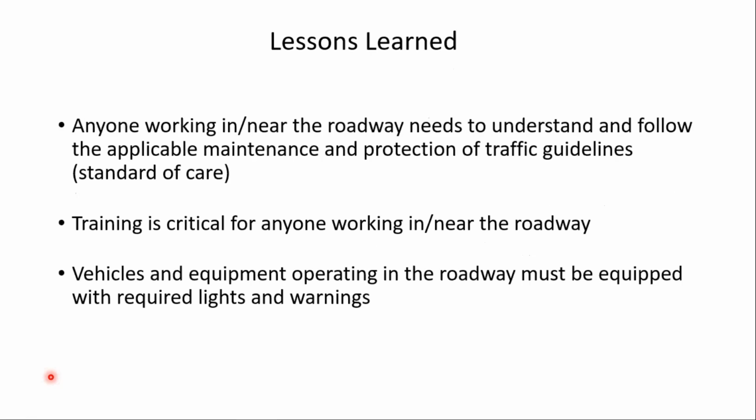So what lessons could we learn from this sweeping activity or incident? Of course, and you all know this, anyone working in or near the road needs to understand and follow the applicable maintenance and protection of traffic guidelines. That's the standard of care, the MUTCD or the applicable state manual. And so training is critical for anyone working in or near the roadway, but evidently this contractor maybe didn't even appreciate that they needed training in that regard.